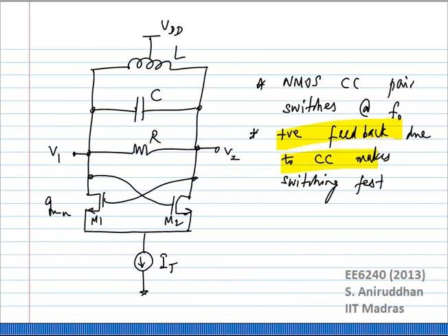So the overall GMs from the active devices are the same, and the noise sources are almost identical. They are not exactly identical, but almost. But one has twice the amplitude compared to the other. So in terms of noise to signal ratio, the complementary pair is much better for a given current. Is that understood?